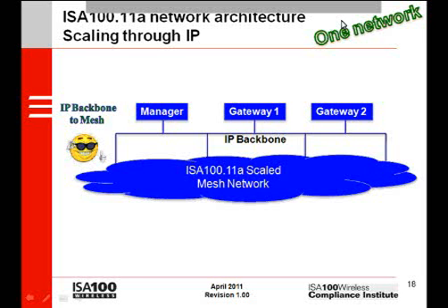There is another computer science advantage that's not so obvious. The scaled mesh with many backbone connections generally operates more efficiently and reliably than several discrete mesh clusters. A single scaled mesh has fewer edges and therefore has fewer edge conditions. In these kinds of radio systems, the edge conditions are deadly, and it's better to design them out of the network at the architecture level.